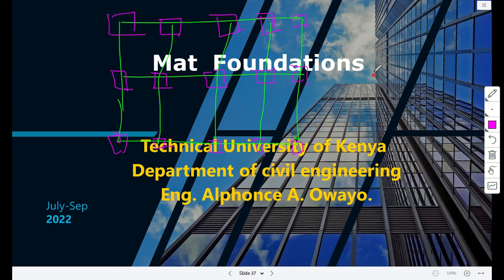So if you draw the cross section of this, you see the column like that, and then the foundation, and probably you draw a cross section, maybe 300 millimeters by 300 millimeters. That's your foundation. So for most of these, the individual foundation or pad foundation is just okay if the soil is good enough and it's economical for most cases.